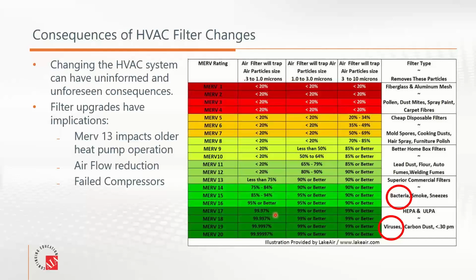They will get 99.9% of all the contaminants that are passing through an airstream. When people talk about MERV 13, they're getting less than 75% of the 0.3 to 1.0 microns, and that's the size of the bacteria and viruses. So you hope for agglomeration that by chance it sticks there and gets caught in the filters.